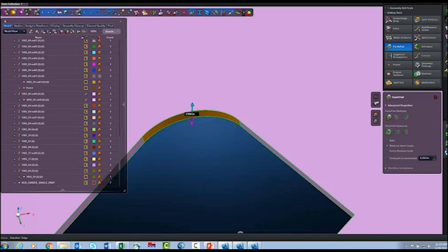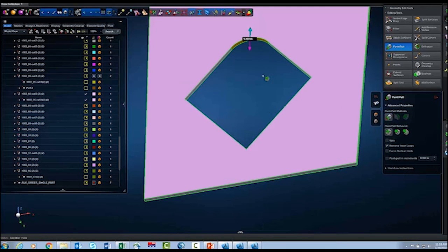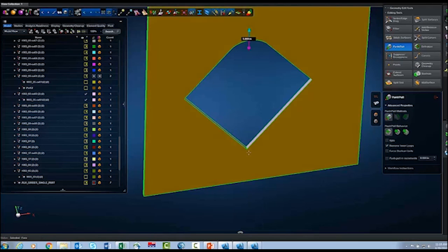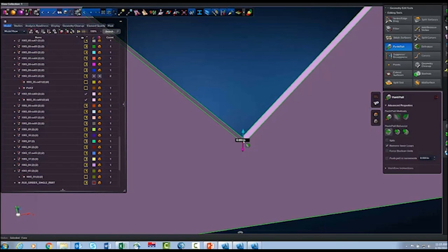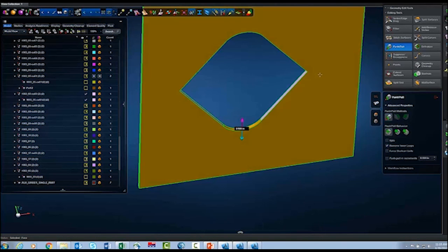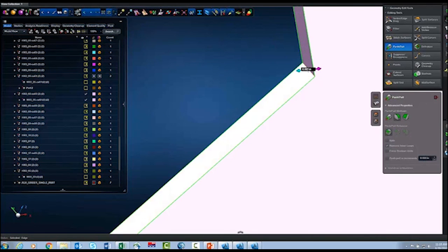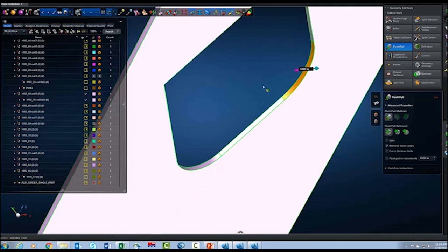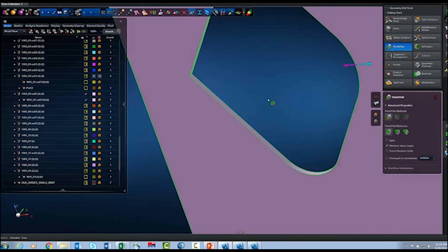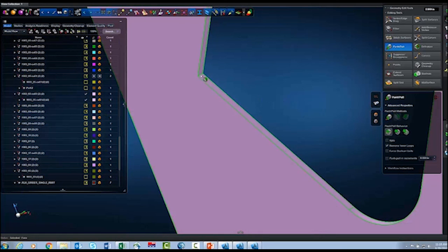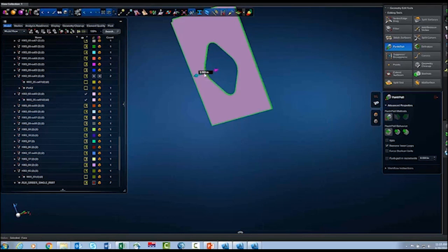Well, the design guy forgot these fillets, so in my estimation, and I'll be the analyst in this case, maybe I want to include these in my analysis. Maybe I think they're important, so I'm going to stick those back in. They were omitted. This is one of the things that Apex allows you to do. It allows you to clean up geometry that's dirty. It allows you to add things that may have been omitted. So I'll just simply add these fillets in. And we've got one more to do. All right, great. So we've got the fillets in.